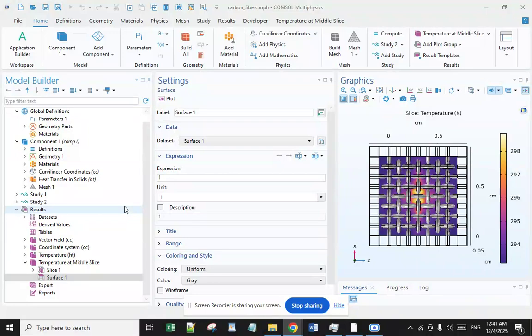The rule of mixtures or modifications could be used to predict the density and specific heat capacity of a composite material, both of which are isotropic properties. The specific heat capacity is also measured using differential scanning calorimetry or DSC. However, it is more difficult to determine the thermal conductivity, which is a property depending on the fiber direction or the direction of nano-reinforcements for particulates with an aspect ratio such as carbon nanotubes, nanofibers, and graphene or graphene oxide,